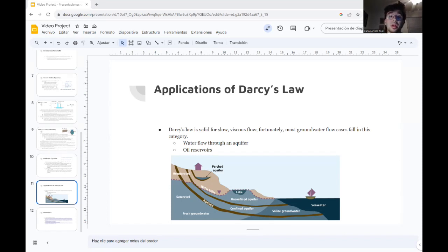In conclusion, Darcy's law is a simple mathematical statement which neatly summarizes several familiar properties that groundwater flowing in aquifers exhibits. These properties include: if there's no pressure gradient over a distance, no flow occurs. These are called the hydrostatic conditions. If there's a pressure gradient, flow will occur from high pressure towards low pressure, opposite the direction of increasing gradient, hence the negative sign in Darcy's law.